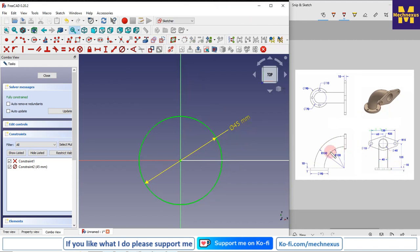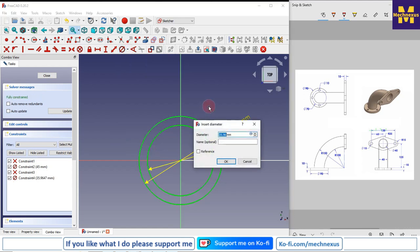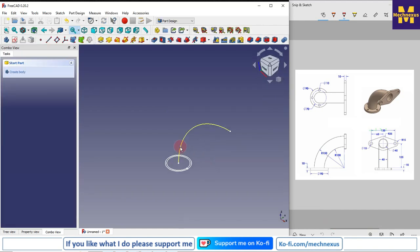and here pipe thickness is not given, so we will take the pipe thickness approximately. So we will set the inside diameter 40, so that we will get the 2.5 mm pipe thickness. Now we will come out of the sketch. So here is our path and here is our pipe.